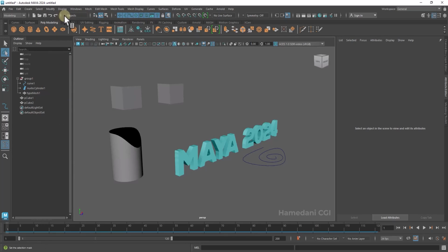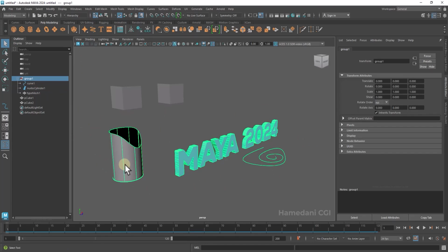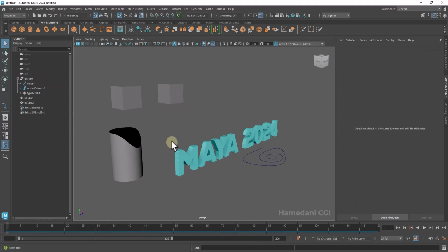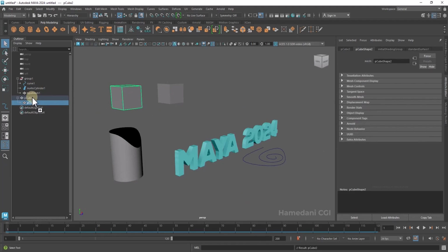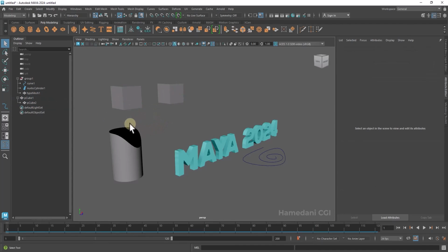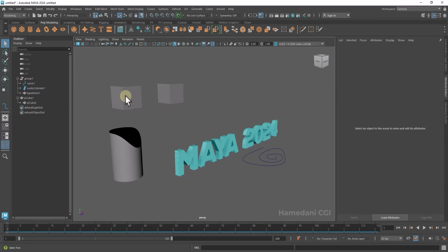And here in the toolbar, what kind of selection? Animation, polygon, NURBS, deform. What type of selection? Hierarchy. When I group this object and click this, you see, nothing. When I click this and select this, you see, I select the group. I group with Ctrl G, or this, or this. I drag with the middle mouse button to cube 1. This is the parent, this is a child. I select the child. Now I select this and select the child. You see?